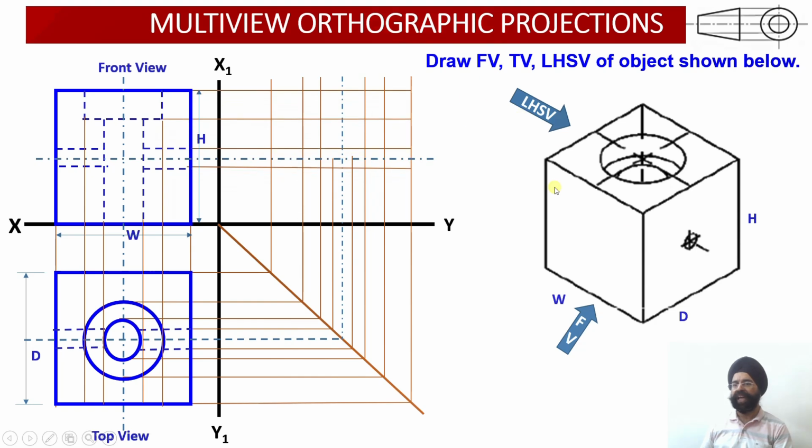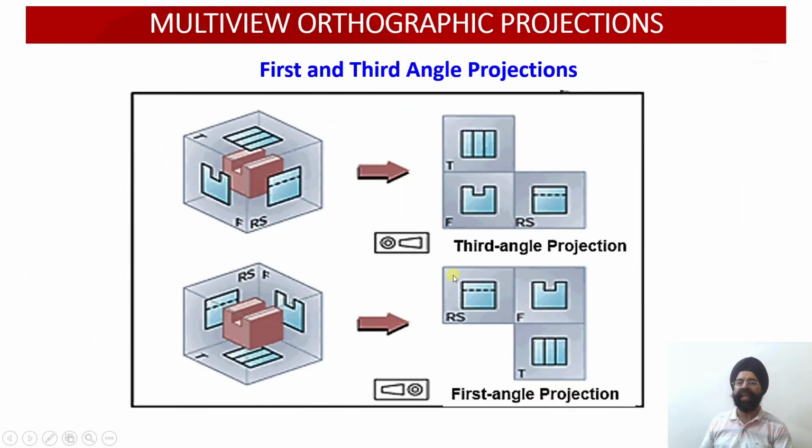So in the left side view, this hole will be visible. This particular bolt section and the shank section are not visible. So the square I can see, the bolt head and the shank section I cannot see, but this circular hole I can see from the other side. So this is my projection in the first angle projection, right? So this is the comparison of first angle and third angle projection.